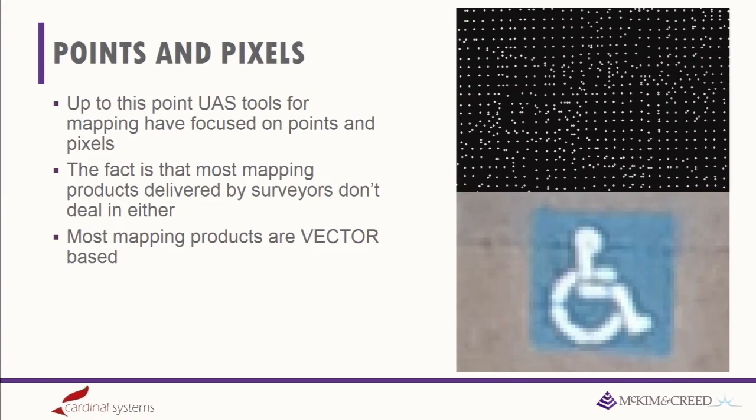So dealing with unmanned systems, we have LIDAR units, we have image-based systems. Obviously, there's a huge price difference between the two. But in both cases, we're dealing with point clouds oftentimes. With the image-based systems, we're using autocorrelation, structure from motion, to get down to a point cloud product that we're then using to create bare earth or give volumetrics, some other information from it. But more or less, we're dealing with either points or pixels for all those applications right now.